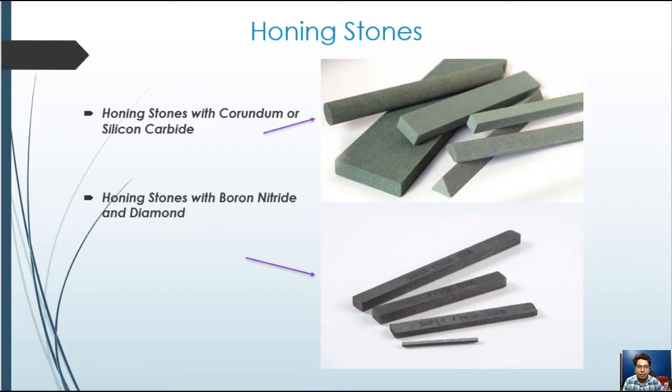Not only stones, but honing oil plays a very critical role in enhancing the cutting ability of the process. That is very clear, as we have studied the effect of cutting fluids in our previous lecture. Now, honing oil is a critical part of the honing operation. In addition to the lubrication, the honing oil contributes by cooling the workpiece and honing tool, as well as by flushing the swarf away from the cutting process. If that is not done, we may get undesired surface roughness in the process.